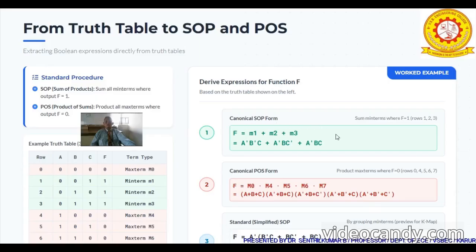Now this is the function without any simplification. You can do the simplification by using Boolean algebra. They have given the example with the idea of canonical SOP, and with the help of Boolean algebra, they have simplified the function. The final function F is equal to A bar B plus A bar C. So the final function can be called a standard SOP function.